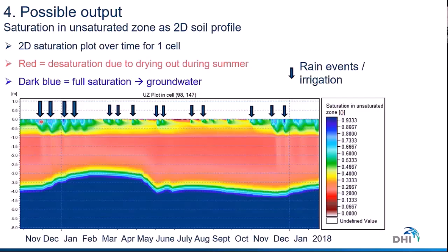In the lower layer you see stronger dynamics, because you have a very sandy aquifer, which tends to be always very unsaturated. And in the top cell you have more loamy sands, which is quite common, at least in North Germany. What you see here is the effect on the saturation in the unsaturated zone for single rain events or irrigation events in the summer. You see the months at the bottom. This can be irrigation amounts or even precipitation. And you can see how well the precipitation percolates downwards and saturates the soil to a certain depth.